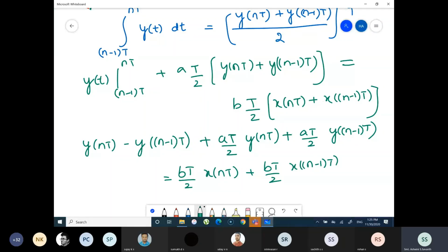Like that we have different methods. For example, in the approximation of derivative, which is the backward difference method, for the first derivative we take the first difference, for the second derivative we take the second difference, and so on. In that way we derive the difference equation in case of a backward difference method. For each method it is different. For bilinear transformation, this is how we do.